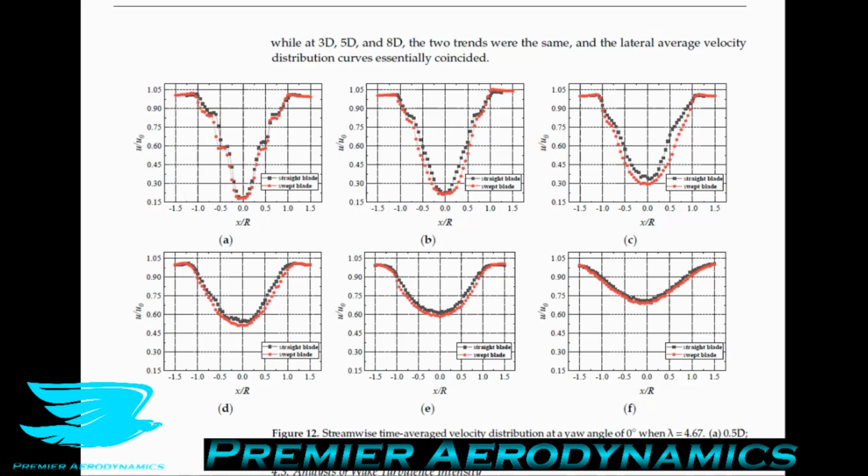The forces that you are getting are not what you think they are. The non-dimensional coefficients that you calculate are not the same as what they really should be. There are all these errors. And in terms of CFD validation, all these erroneous measurements make CFD much harder, because when you're trying to validate your model, you're using different densities, and you're going to get different forces. You're going to get different velocities, different wake profiles, everything, different vortex breakdowns, different von Karman street formations, everything.